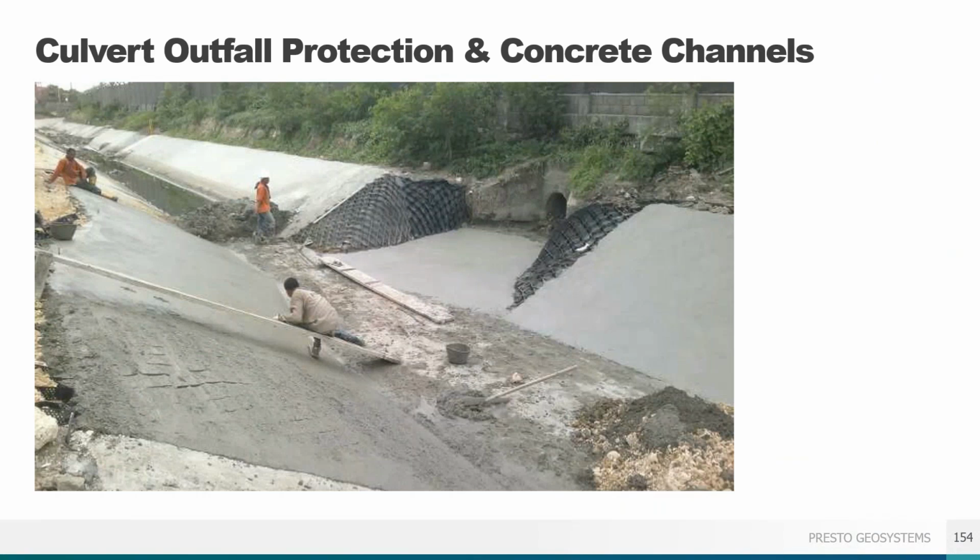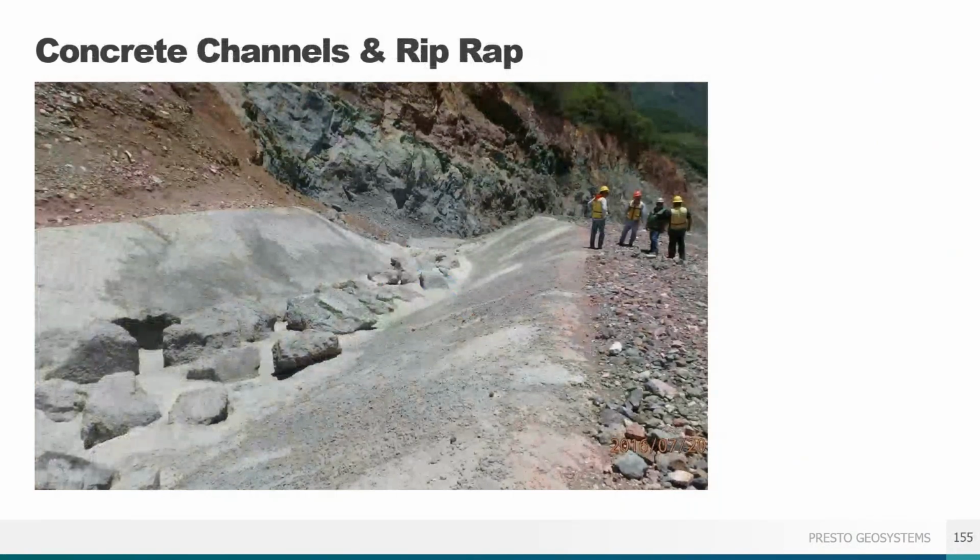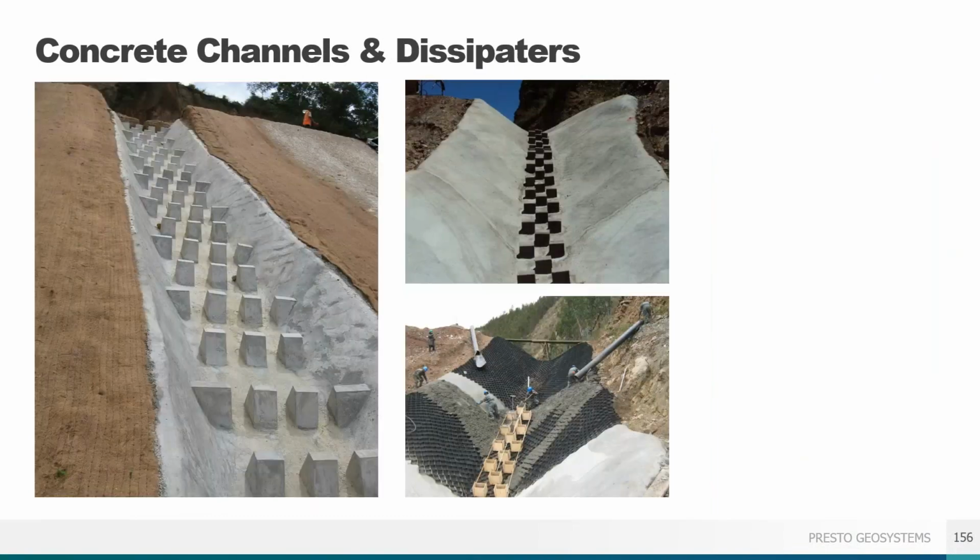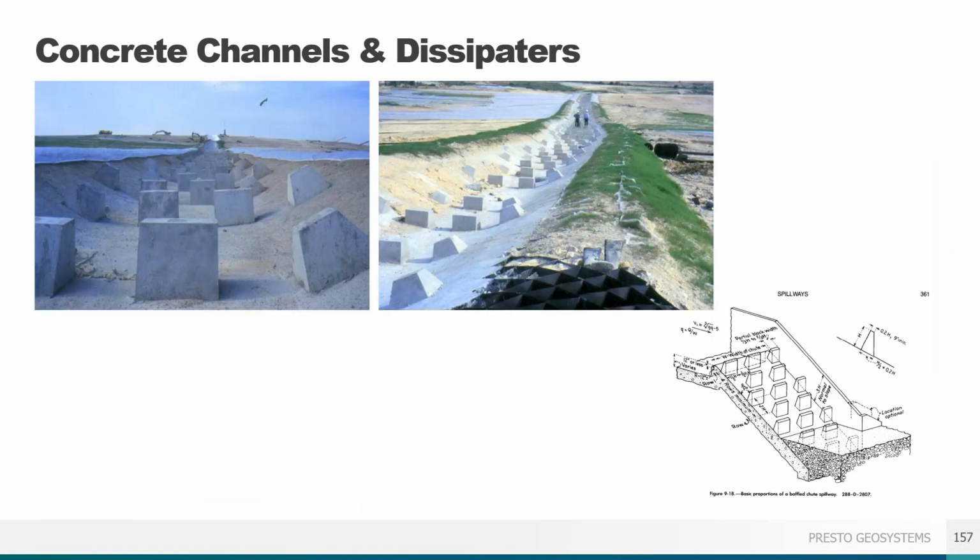For concrete channels, another pro tip is to use the GEOWEB as your formwork and have it contour as needed for your outfall structures. The GEOWEB channel system is flexible enough to modify the structure. Here's a technique tip of grouting in large riprap in a rockfall area of a mine closure channel. Or you can add energy dissipators directly as part of your channel design.